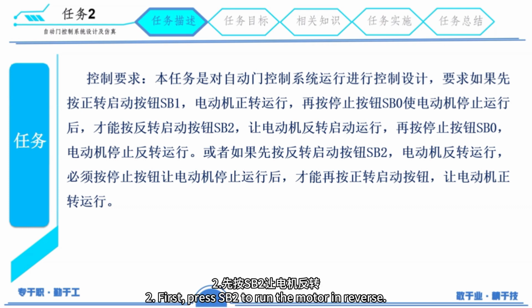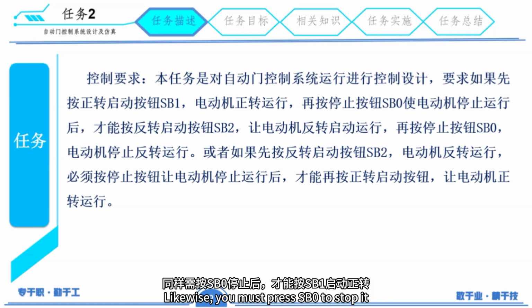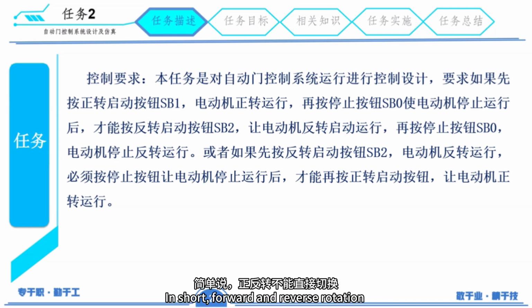Second, first, press SB2 to run the motor in reverse. Likewise, you must press SB0 to stop it before pressing SB1 to start forward rotation. In short, forward and reverse rotation cannot be switched directly. The stop step is mandatory.